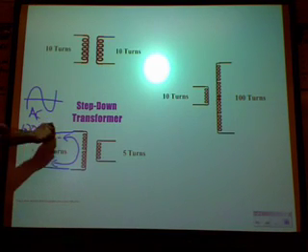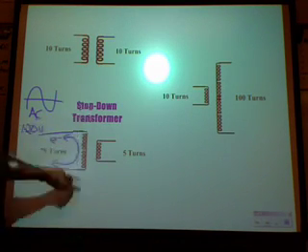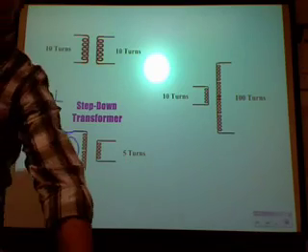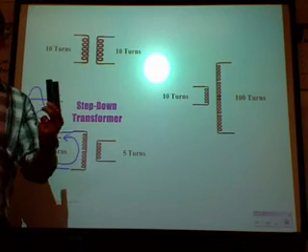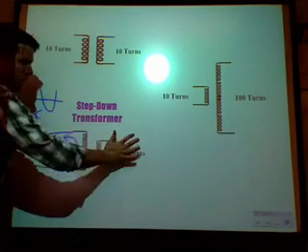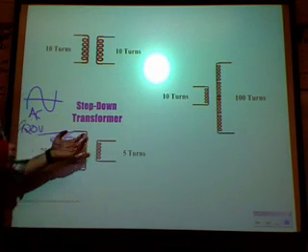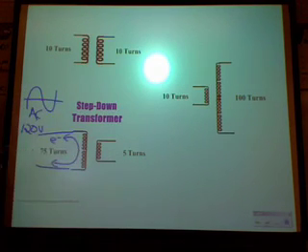So the electricity flowing through the wire and changing directions is the same thing as a magnet moving back and forth. I just think that's so cool. Because otherwise, if I want to generate electricity, I've got to have my magnet moving or my coil moving. There has to be physical movement. Here, I don't have to do that. I can pass the electricity over to this wire and the wire's standing still. Those two coils are sitting right next to each other and standing still. What's moving are the electrons back and forth, making moving magnetism.